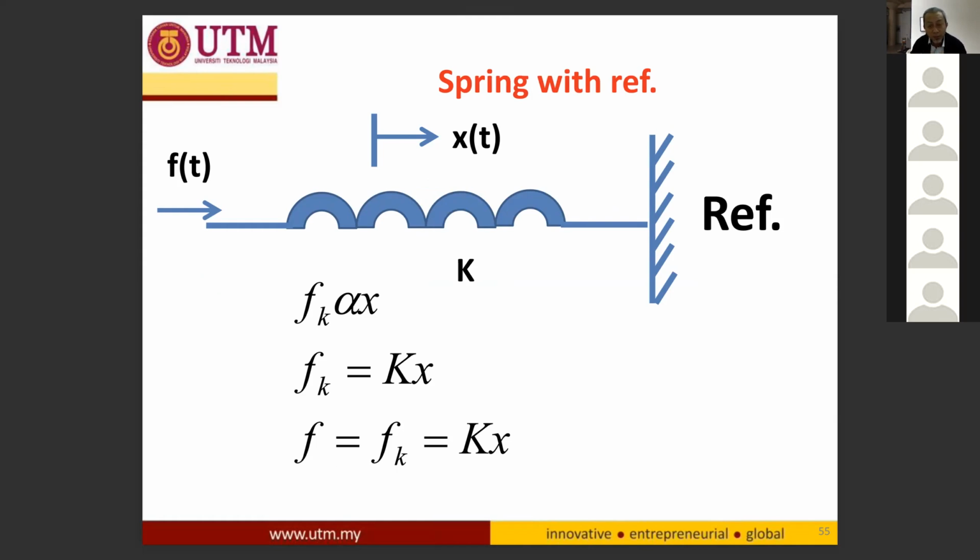Every item, mass, spring, and damper, has its own age. The older the items, the less they can maintain the constants K and B, the spring constant and the viscosity, because of the aging factor. That's why when you drive an old car with a 10 or 15 year old suspension system, you will not feel it soft anymore. It becomes hard, and it's not comfortable when the car hits a bump or a hole on the road.